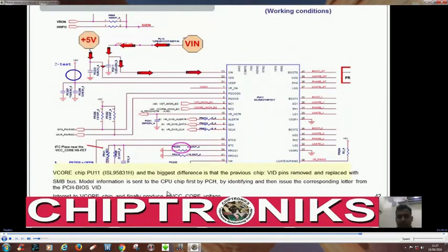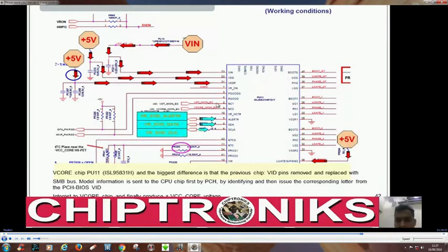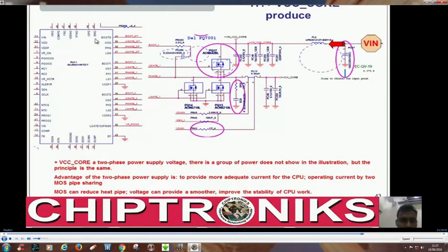And everything. Yes, you can see over here VIN is coming, right? And VDDP and VDD, and VDDP has got its voltage. Plus 5 is connected with the gate, and SVID data from the processor is coming over here. VR on is here, VR on, okay, and then this regulator will generate drive high and drive low to switch these MOSFETs to generate the VCC core.